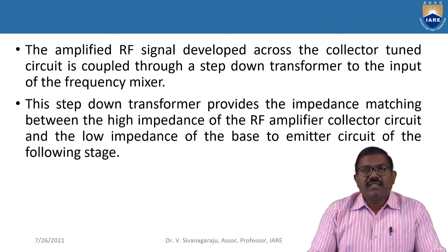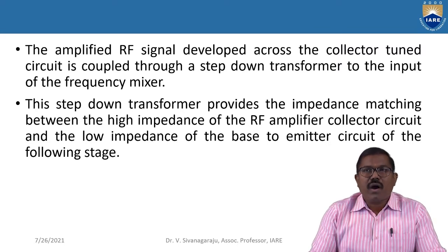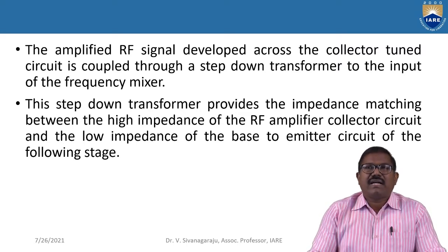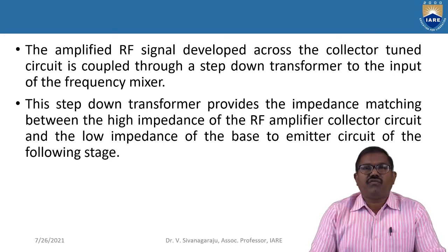This step-down transformer provides the impedance matching between the high impedance of the RF amplifier collector circuit and the low impedance of the base to emitter circuit of the following stage.